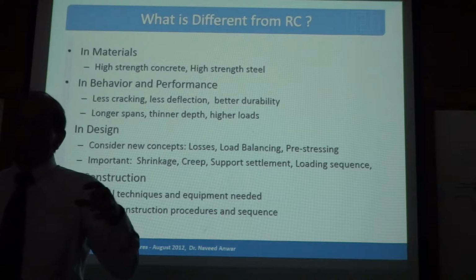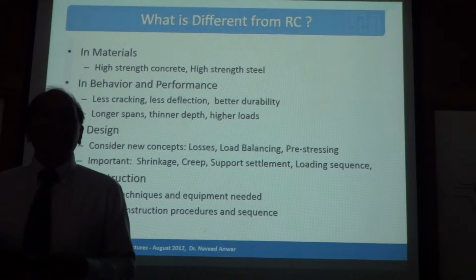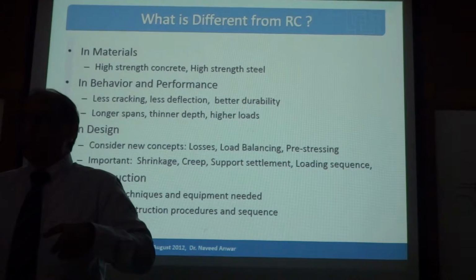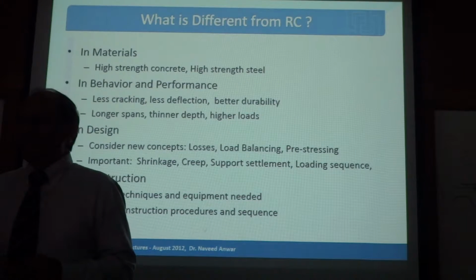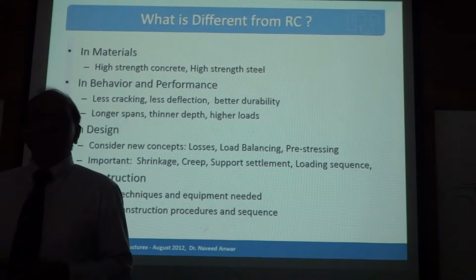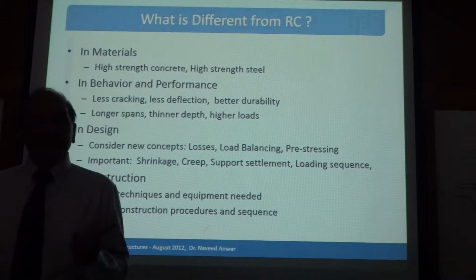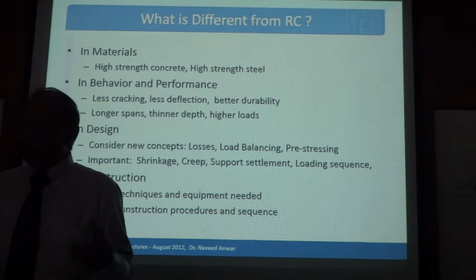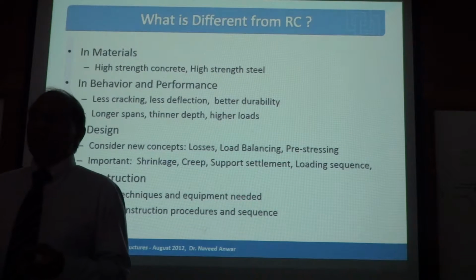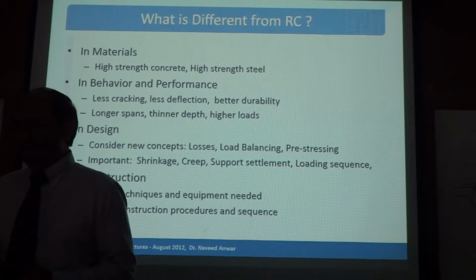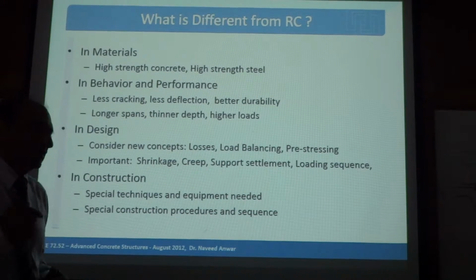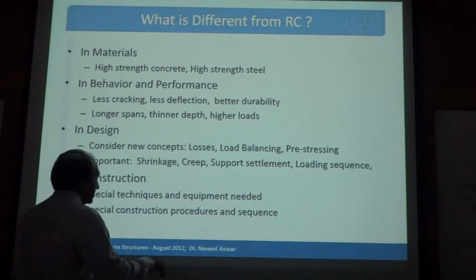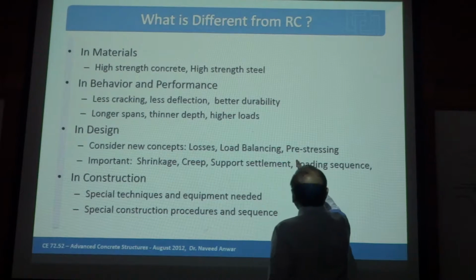Normally when you put reinforcement in a concrete beam, it's passive steel. It just lies there, waiting for the beam to be loaded so it can take tension, waiting for the concrete to crack so it can take tension. But pre-stressing is active steel. It puts the force into the concrete before the loading comes in.